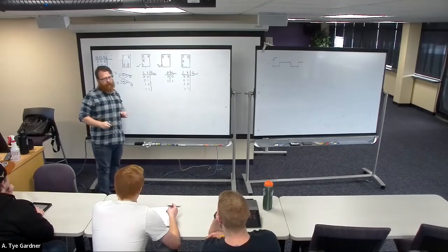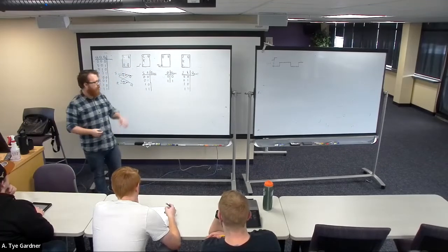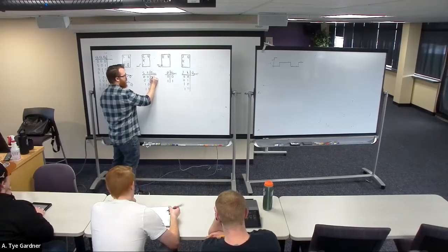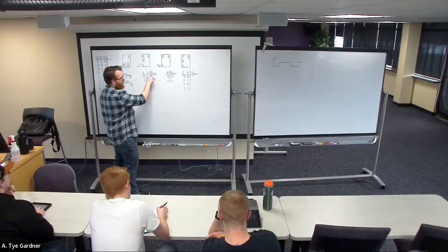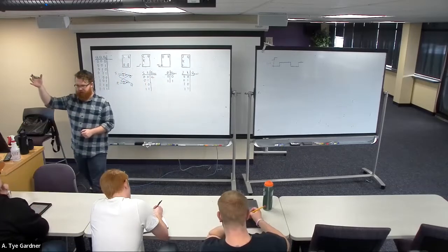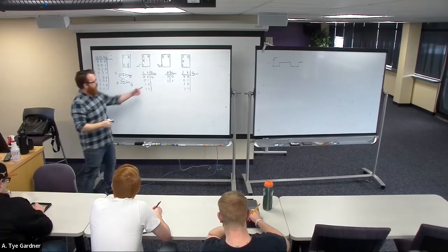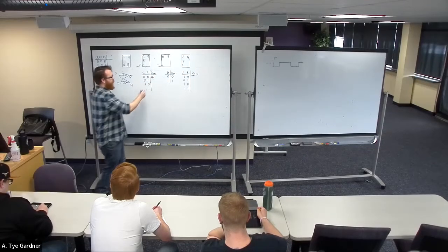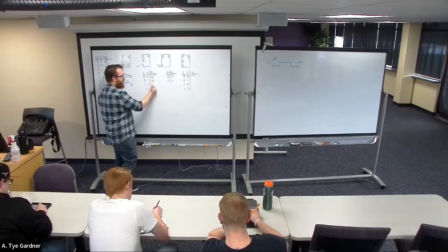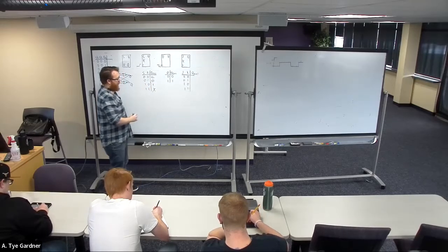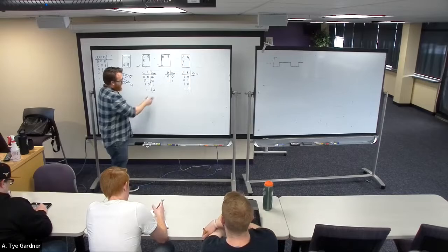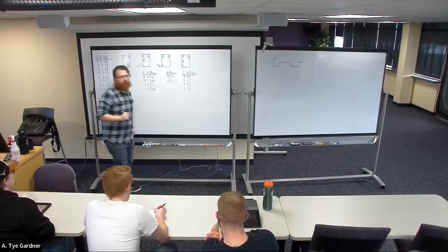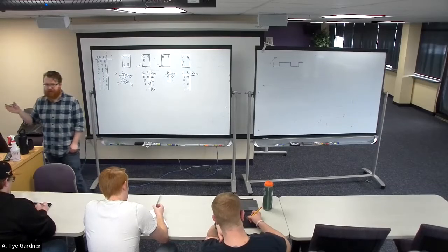We can build SR flip-flops. It's not as common. They do the same thing. If they're 0, 0, we take Q at n+1, meaning the next rising edge. The next time that I see an update, we stay what we used to be, Qn. So the next Q stays the previous Q. If we reset, it goes to 0. If we set, it goes to 1. If we do both, it is X, which if we want to talk more in Vivado terms, right? U is a good character, undefined. We don't know what it is.